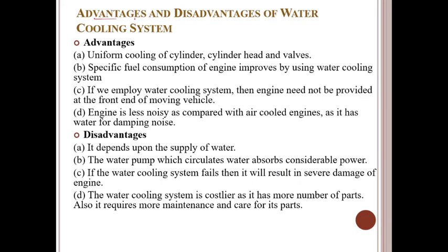What are the advantages and disadvantages of this water cooling system? First we discuss the advantages. There is uniform cooling of the cylinder, cylinder head and walls. Second, the specific fuel consumption of the engine improves with the water cooling system. If we employ water cooling, the engine need not be provided at the front end of the vehicle; we can put it at the back, no problem. The engine is also less noisy compared with an air cooled engine, as the water damps noise.